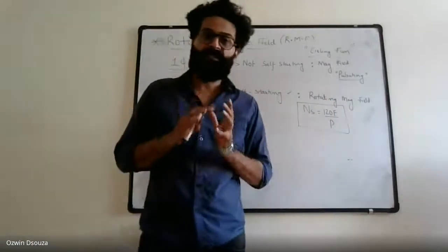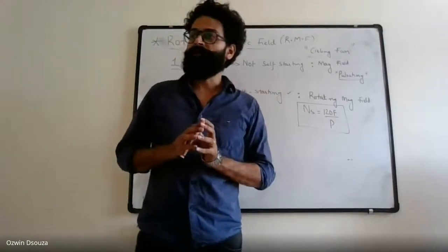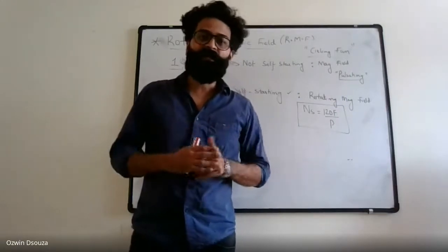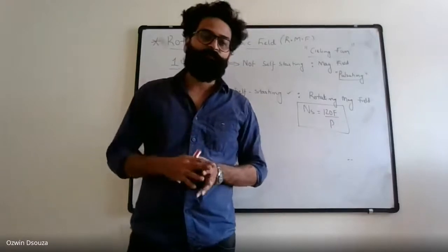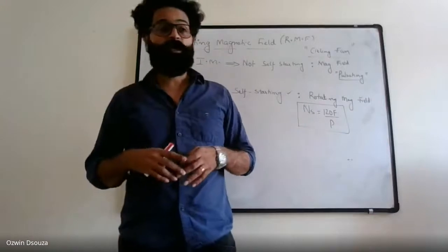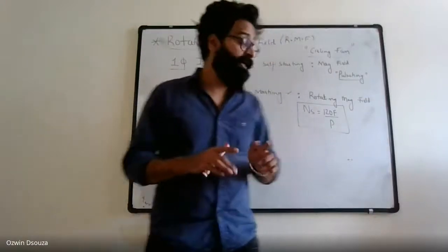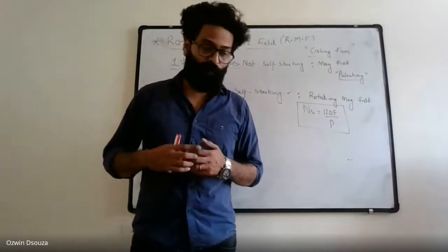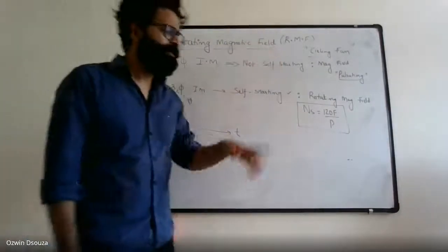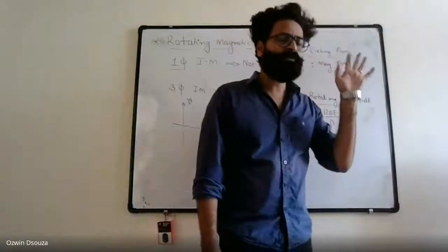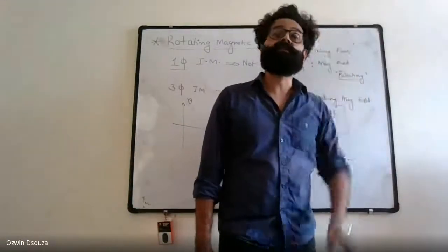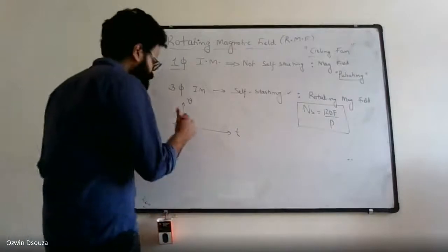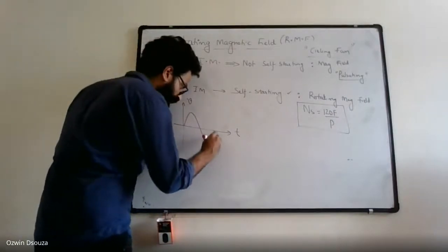That is the reason ceiling fans are always used in combination with a capacitor. The capacitor basically acts like a starter or starting mechanism. So you need a capacitor in order to start a single-phase induction motor. On the other hand, your three-phase induction motor doesn't require a capacitor. If you connect a three-phase AC supply, the motor simply starts. That is the reason in your house, you will find a capacitor connected to the ceiling fan motor. Now, single-phase AC, this is how you represent it, right? One positive half cycle and one negative half cycle.